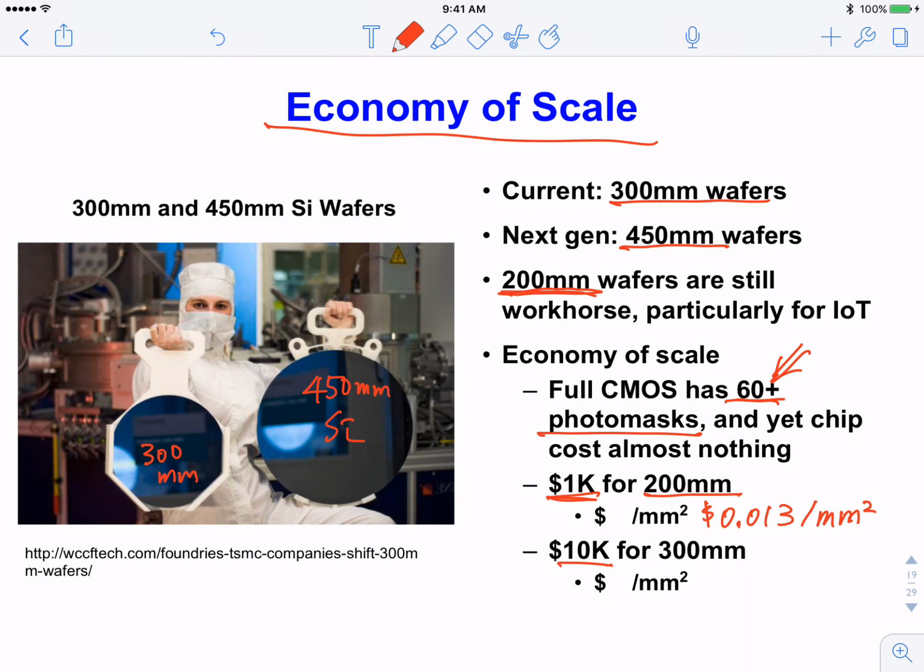Well, again, if you look at small areas per millimeter, it is about, I think, $0.14 per millimeter square. So for this reason, we say basically chip costs nothing. Everything else is what's surrounding the chip. The design cost, the cost of human designers, packaging, the cost of putting them into a package. That turns out to be more than the chip cost. The overhead is about 90% of the cost. The chip itself, despite the complexity, really costs nothing unless you're making some really special chips.